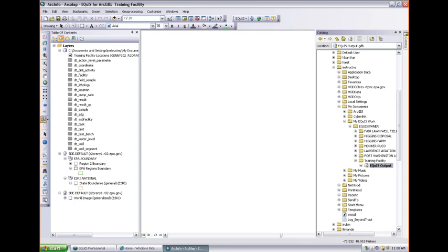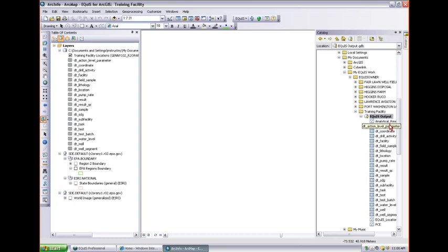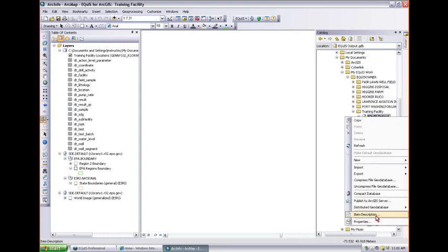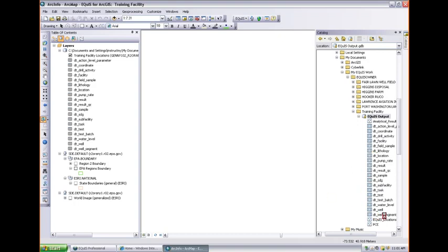If you know what a shapefile is, geodatabase is basically like a folder full of shapefiles, right? ESRI wouldn't agree, but that's the way I think of it. You could also put tables in this thing. On disk, it just looks like a folder, and you can copy that over to other folders. But it's best to use ArcCatalog for managing it, even though it does look in Windows Explorer like a folder, because you'll see a bunch of long, weird named files. Don't go in the folder. Use ArcCatalog. And again, the easiest way in 10 to get to it, you just hit this, bam, and it shows you where it is. You can look at the, I didn't even talk about metadata.